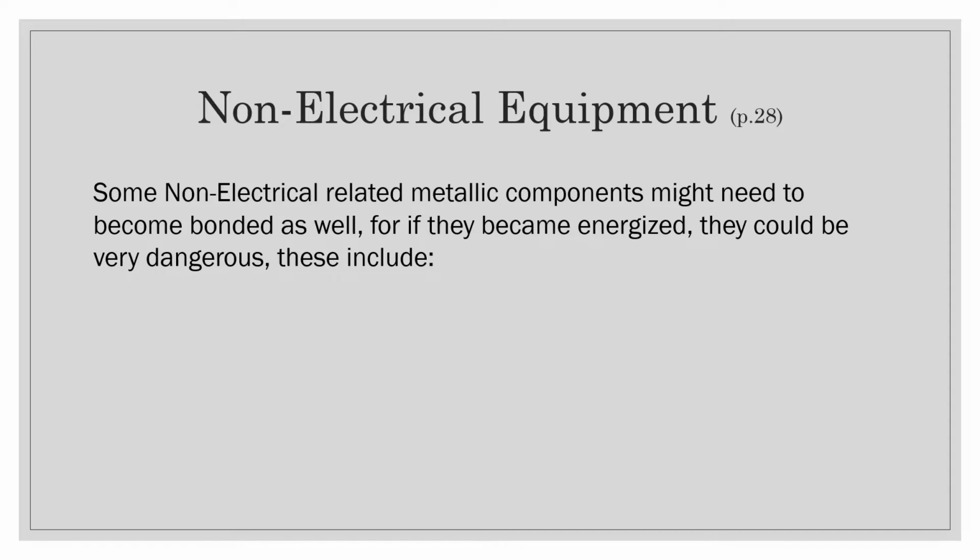Okay, the other thing that addresses, and this is found on page 28 of module L1, is the importance of bonding non-electrical related metallic components. There are a few situations where it can be very dangerous if components within your house became energized or touched a live wire if they were not bonded to ground.